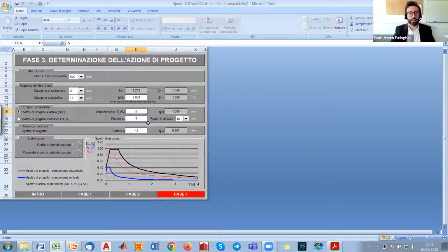As we mentioned last week, according to the Italian building code, the elastic spectrum related to 5% damping is the only one with scaling factor eta equal to 1. So if we assume the elastic spectrum with a unit scaling factor, we will scale it directly within our design procedure with the proper definition of the damping ratio. This is very important: we need the elastic spectrum at 5% damping.